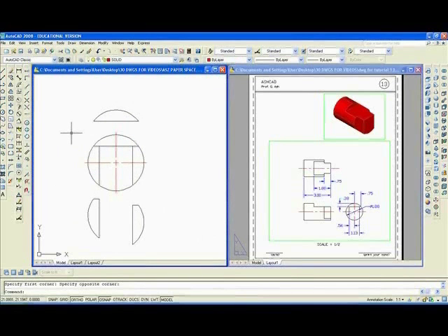First, I think what I want to do is polyline edit. Make that a polyline, yes. J, enter. I'll select both lines. Hit enter twice. Repeat the command. Polyline edit this line. Yes. Join, enter, J, enter.